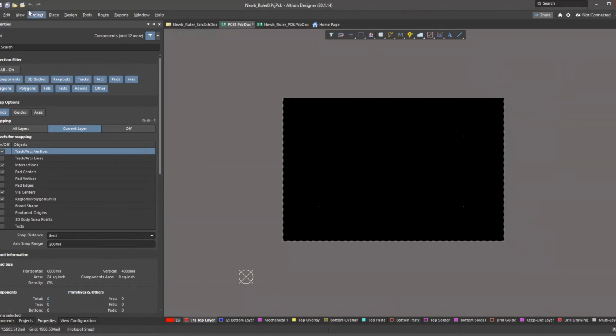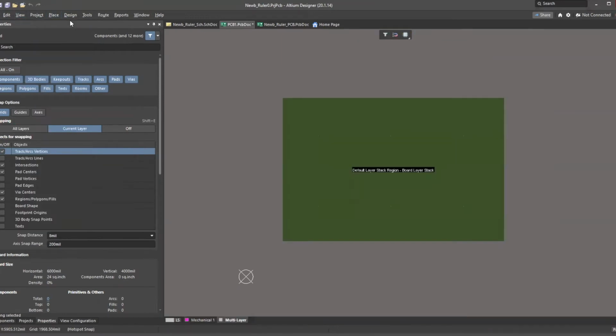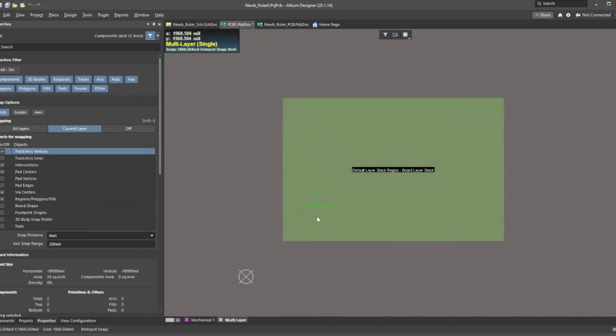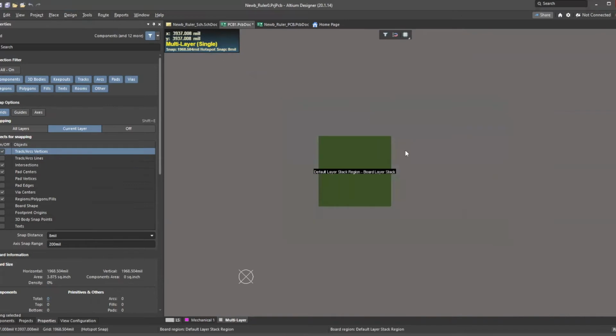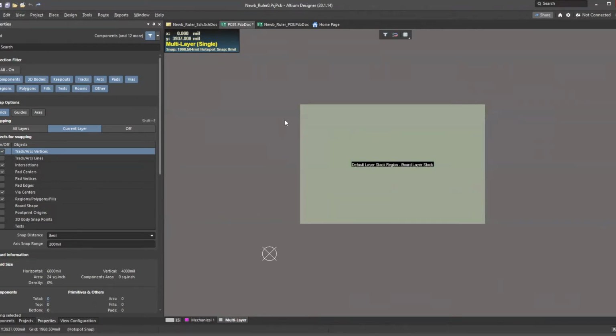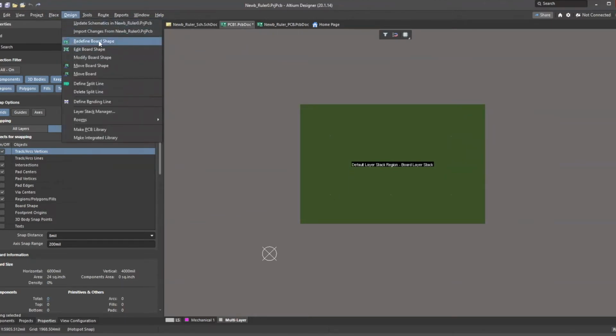Now we're going to go to, let's see, board planning mode in view. Then board planning mode, while the board is green, design, redefine board shape. Now, when you're redefining board shape, you have to click to define the board, and see, I've redefined it. You might have just noticed that because I made the grid so huge, I can only change the board shape in increments of 5 centimeters, which is going to be useful because my board dimensions are in 5 centimeter increments.